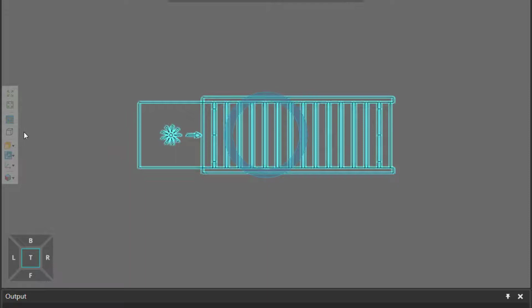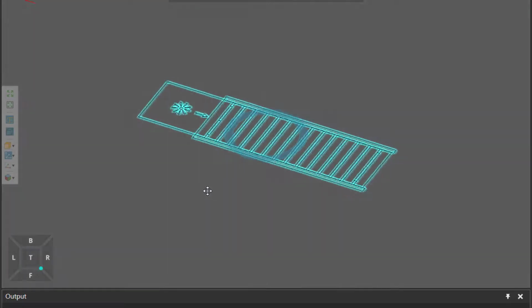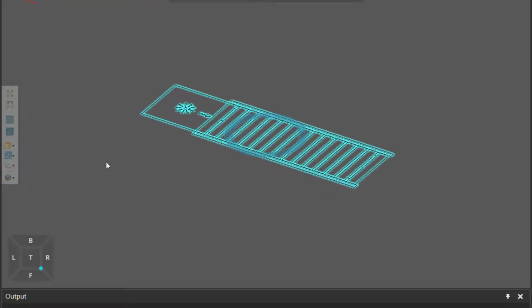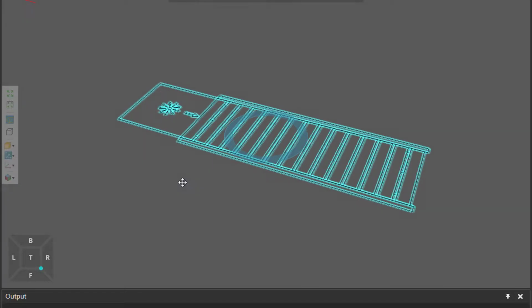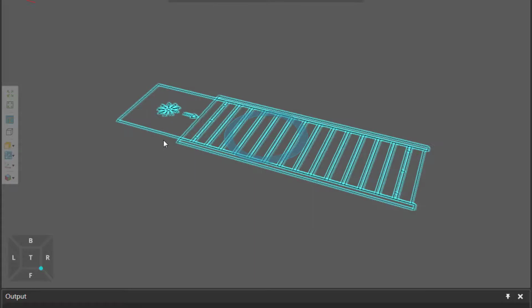Great. Now, when you import the drawing, you have to be careful what projection you're using in the 3D world. So notice here in the 3D world toolbar, I'm using perspective. Orthographic is not turned on, but you can turn it on and work that way if you want to. So here's orthographic. What if I change it to perspective? You can see a change happen there. So I will keep it in perspective. I'll now add the components I need. So I need a feeder and a conveyor.